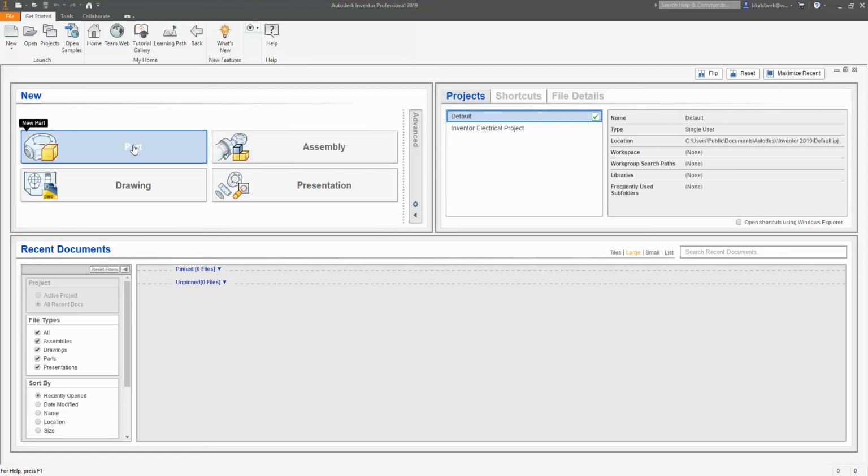So you have parts, that's like an individual, and then you have an assembly. So you take multiple parts and put them together to form an assembly. So you have one, and then you have a group. Once you finish either a part or an assembly, you can take them and put them onto a drawing. That's basically a fancy way of doing multi-view drawings. This is where you can do top, front, right side views. You can also put dimensions. You can do materials lists, and you can do lots of things with a drawing, but it makes things look very official, what you would typically turn into your client or somebody for manufacturing.